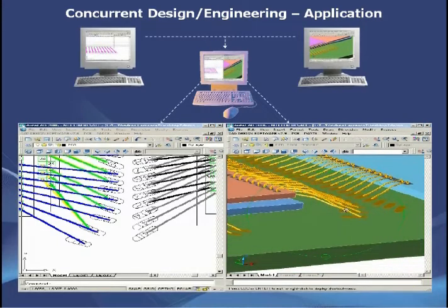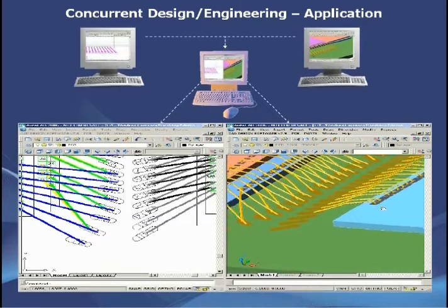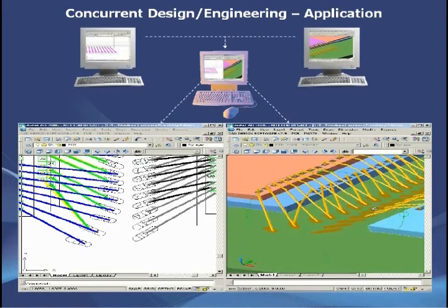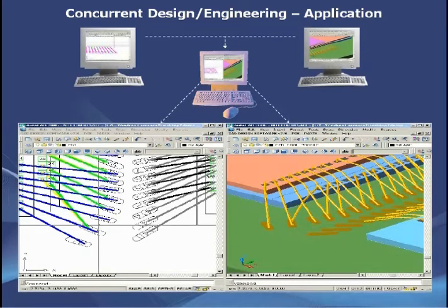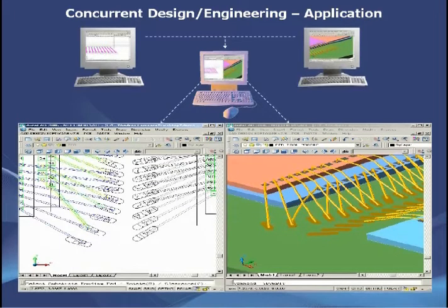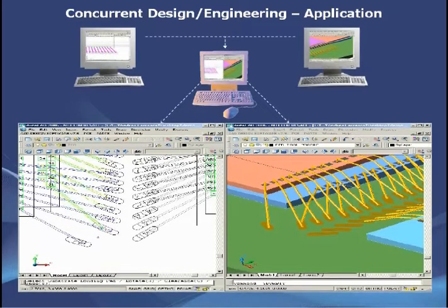At the same time, the designer wants to move the substrate bond fingers in a different way. This change in the 2D environment is reflected in turn in the 3D environment, also in real time. Based on the benefits of this type of concurrent activity, the designer and the assembly engineer can decide on a good wire bond fan-out that will work for both the substrate and the assembly manufacturing.